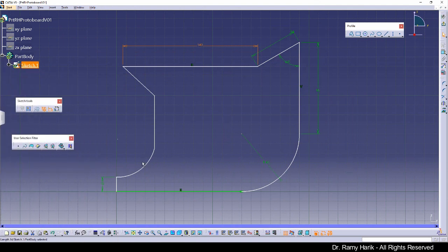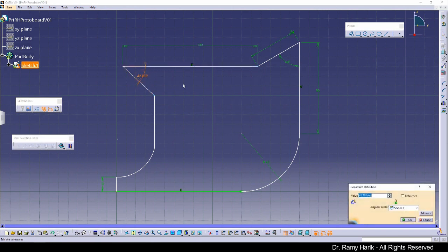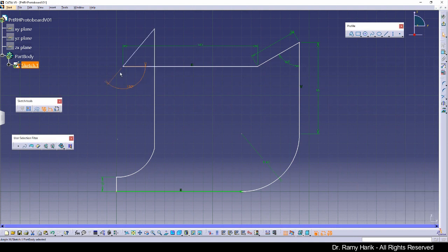So let's continue putting what we have at hand. There is a dimension of 140, we did that. There is an angle of 30 degrees, so I'm gonna click here, select. So this is good. If you have a purple, this means that this constraint doesn't add anything to it. This means that you already have it, and you can see we have the 140, 140, but we were clicking in here so that we click back in here and create the angle that we have, which is equal to 1. Oops, it was supposed to be 30, not 130. Here we go, this is 30.